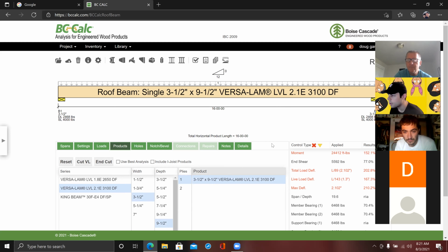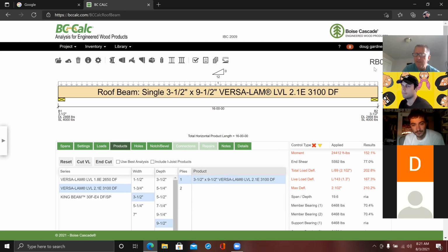It's very red. Exactly what I was fishing for, Landon. Red. So this is what the inspector wanted. Does that make sense? Like you can see why they would want that. And notice the percentages. Notice the shear, which again, I'm not going to explain all this, but notice it's 77%. Oh yeah, no problem. But notice the moment, which you know how to calculate, 152%.